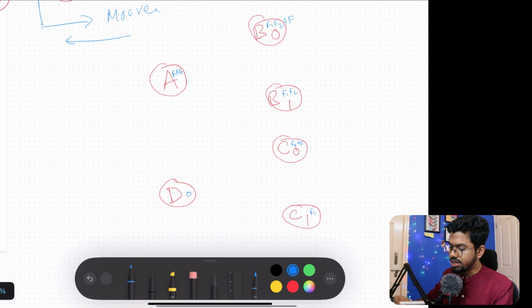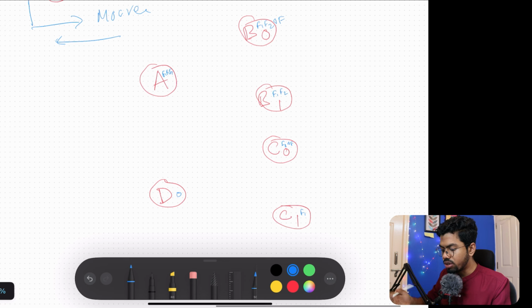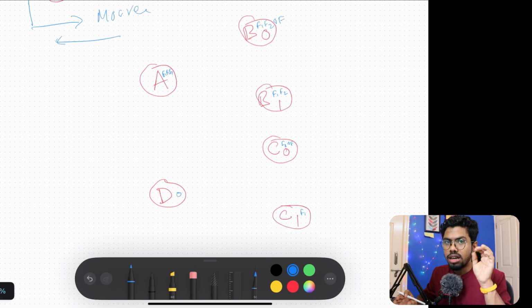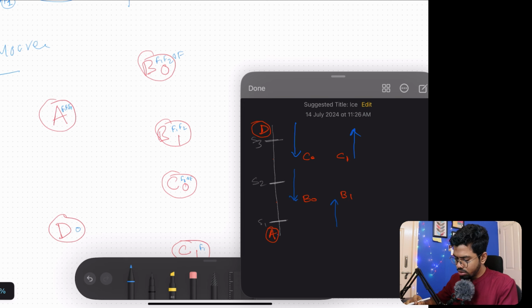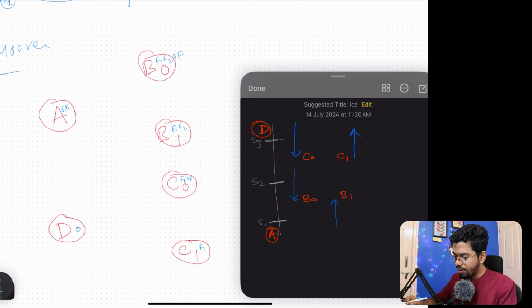So see here, it is so simple. With the state I know the output only. Now my main work is how to transition from one state to another state with the help of input, and output is already defined here. Now you just concentrate on both things, left and right. On the right side you have your states, your water level, and on the left side I want to design my state transition diagram. So from A to B0, when will you reach? From A to B0, when will I be reaching?